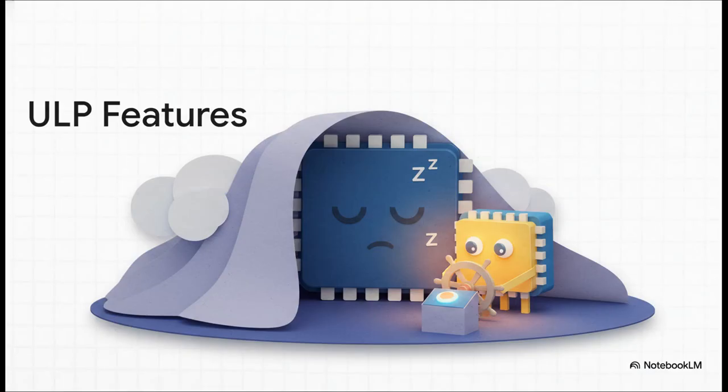During these deep slumbers, the ultra-low power, or ULP, coprocessor essentially takes the wheel. It runs on a highly efficient 8 MHz clock to independently monitor sensors, like the touchpads or the ADCs we discussed earlier. It'll just quietly do its thing, and it only wakes up the main, power-hungry system when it detects a critical threshold has actually been reached.